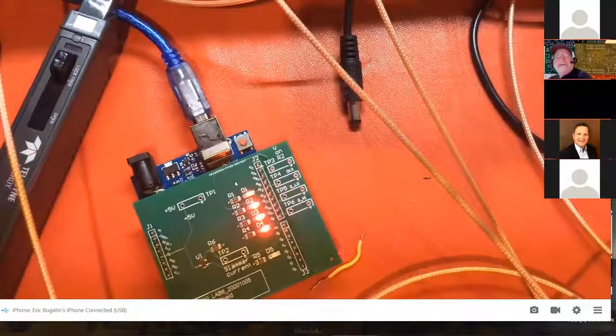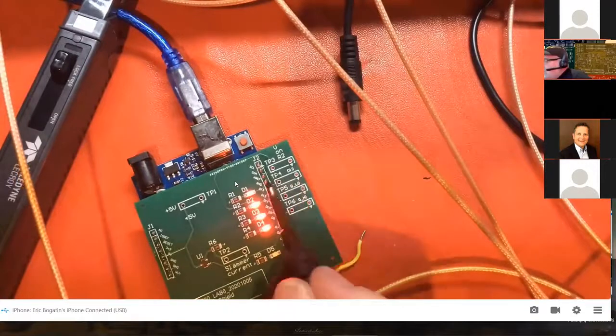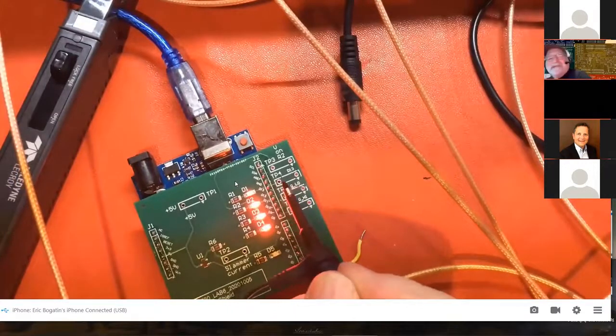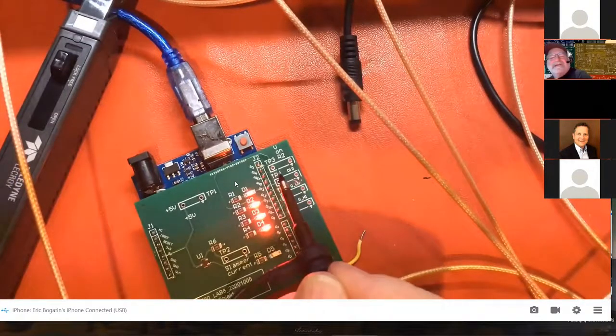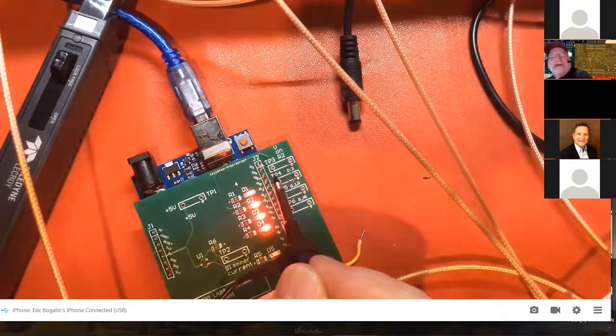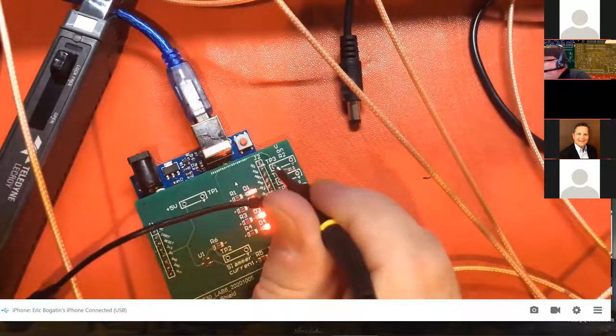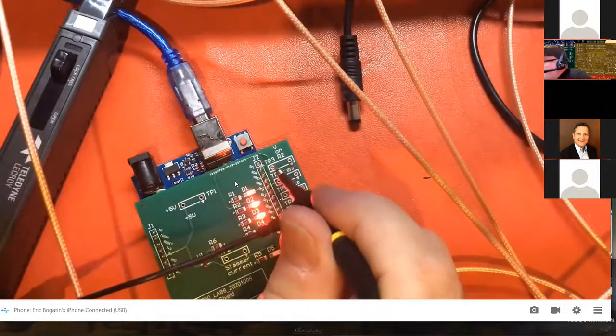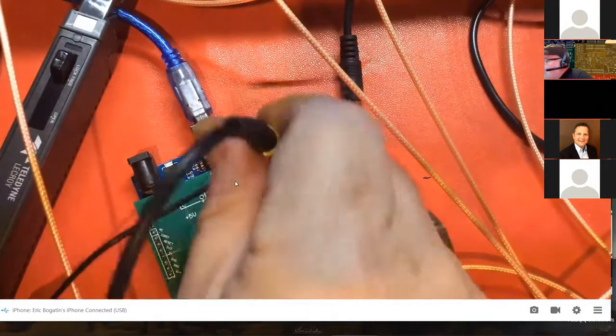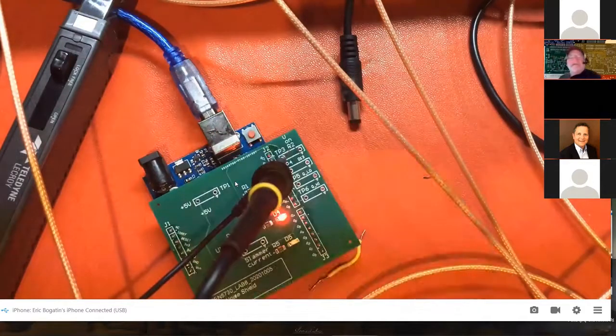I have test points that are conveniently on 300 mil centers, which happens to be the spacing between the signal tip and that ground lead. And this is one of the principles we teach in our classes, design for test and bring up. With that spacing of 300 mils, that 10x probe fits in there really nicely and kind of stands up by itself.